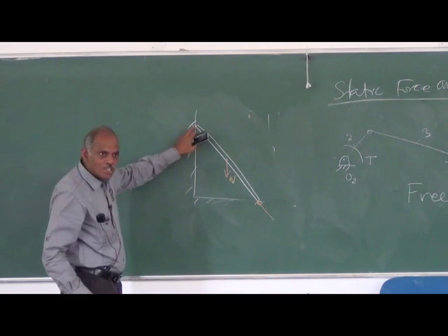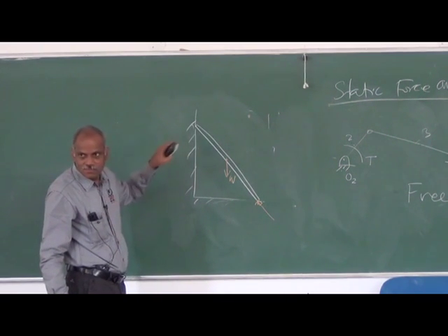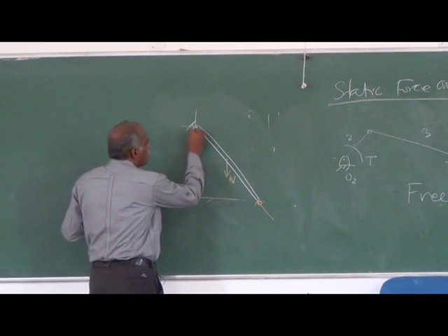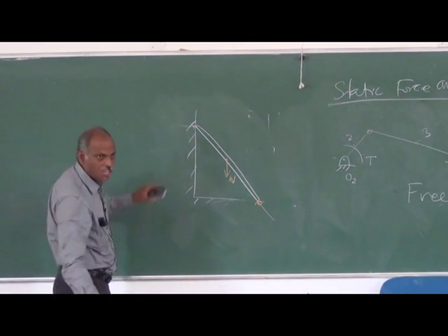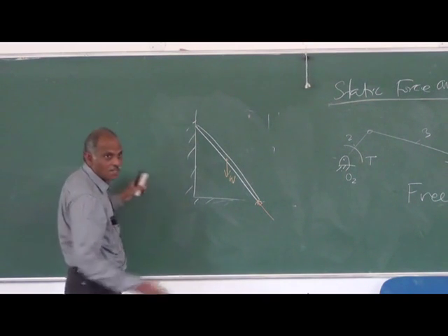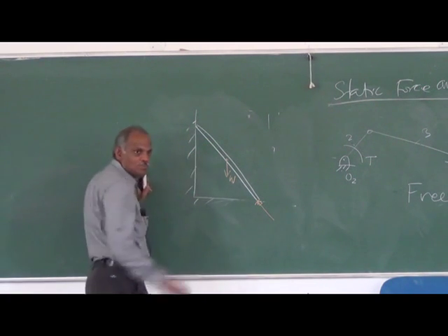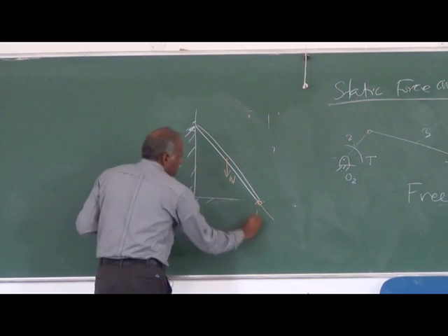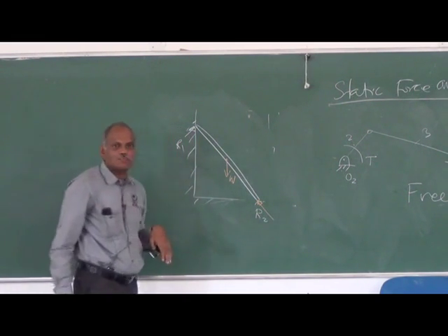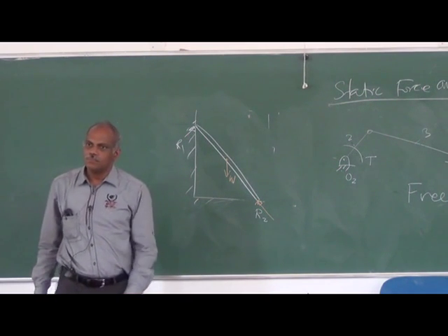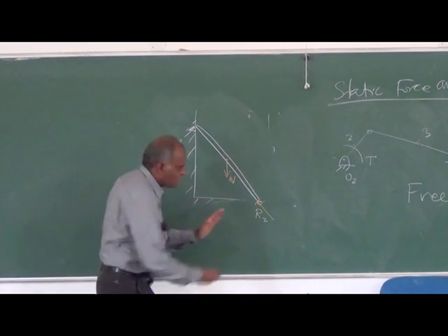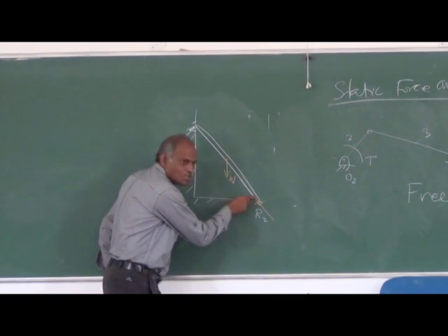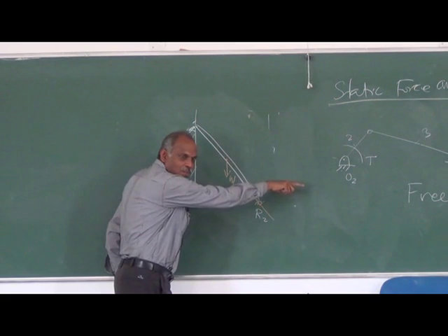So when it is a frictionless surface, the reaction will be normal to it. If there is friction, then you have to apply your mind to the direction in which it will tend to move, then your reactions will be like this. So your R1, R2 will be there. I cannot draw this R2 in this direction because the ladder will tend to slide in the opposite direction.